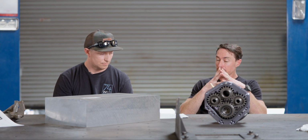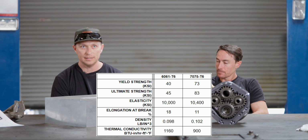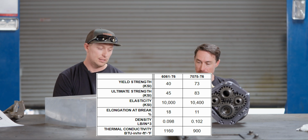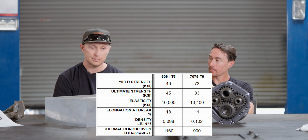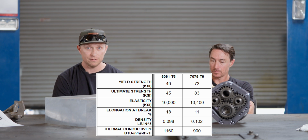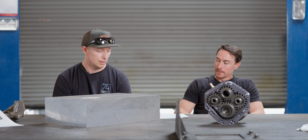Tensile and yield. Yield strength on 6061 is going to be about 40 KSI. That means thousands of pounds per square inch, so 1 KSI is 1,000 PSI. Again, 6061 you're at about 40, 7075 you're at about 73. Ultimate strength you're looking at 45 for 6061, 83 for 7075. So it's significantly stronger on both counts.